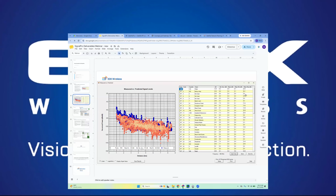And in this case, you can see we've got clutter loss turned on. So we're seeing a table of all of our clutter values and how much clutter loss is being applied to the subscriber location to account for potential nearby obstructions, the fact that they might be indoors, whatever.